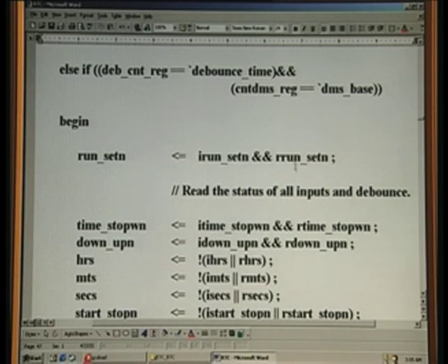So now when the subsequent sample, that is the current time now, suppose the push button has been pressed in between, suppose 0.1 second back it was 0, that means this was 0, and now after 0.1 second this is going to be read. In between, whatever be the time when this goes high, it will be reckoned only at 0.1 second now. It may not be really 0.1 second, but here it is, as per I think debounce time, 3 millisecond delay.